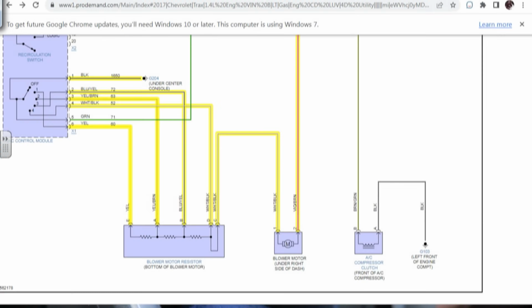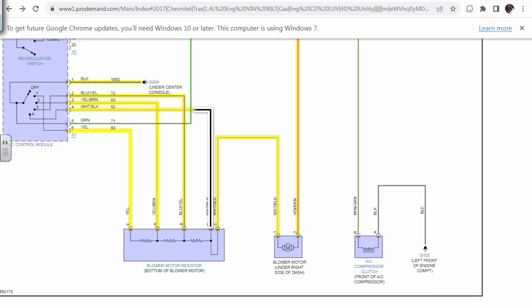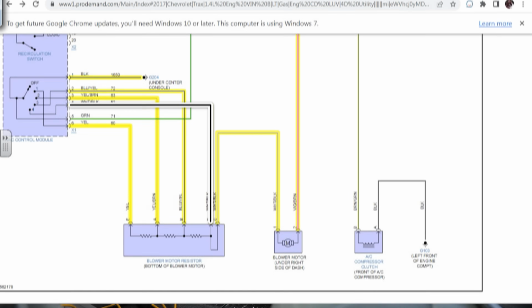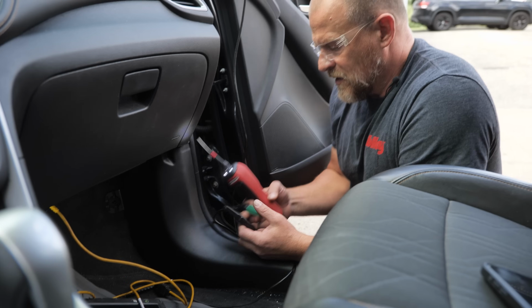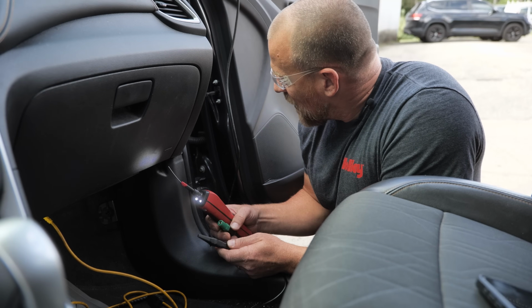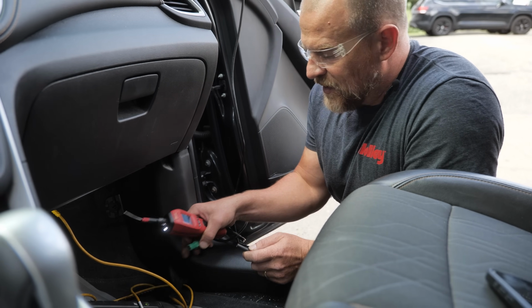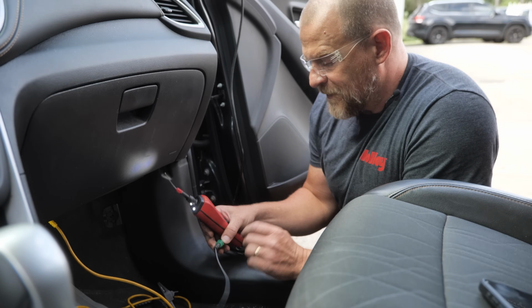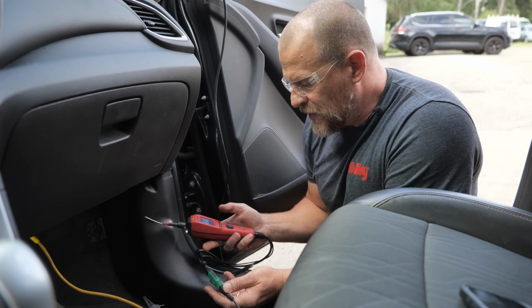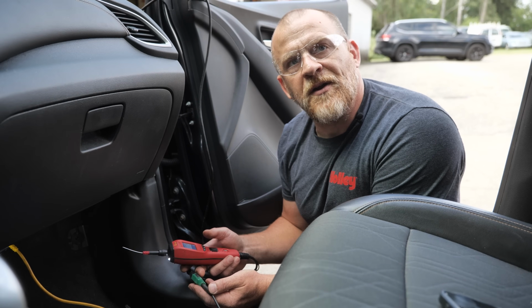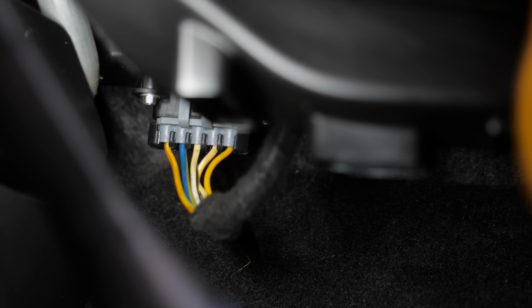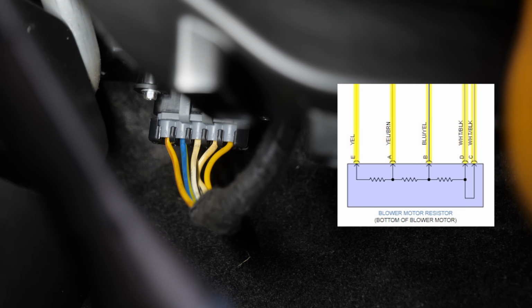So what I'm interested in is the second white black wire. It looks like pin D. I want to know the voltage level on that white black wire, it's going to tell me really everything I need to know. From this point, so I don't have to fart around with the door jamb and this ground, we'll use the power probe ground, which I really like with this tool. That goes right to battery ground now for my lab scope. Yeah, you can see the two white blacks are a little bit discolored, but it would be from left to right.